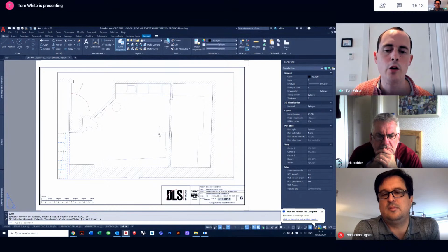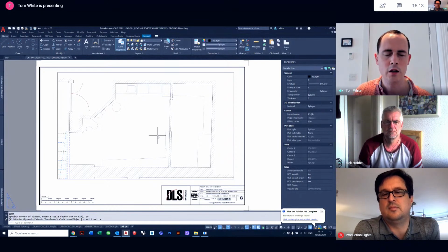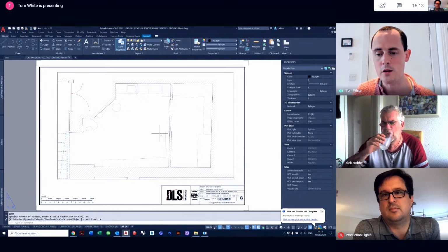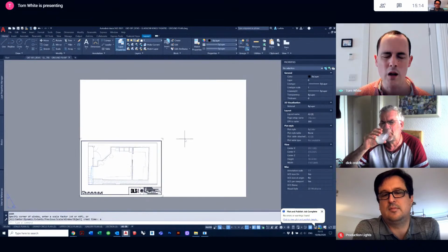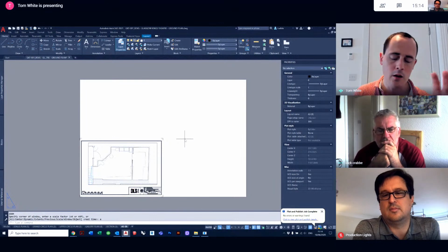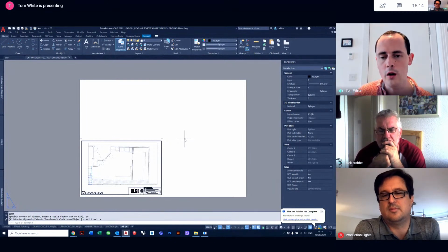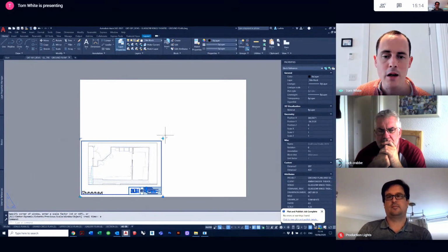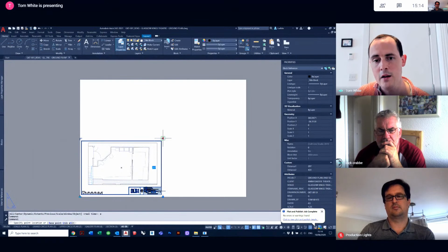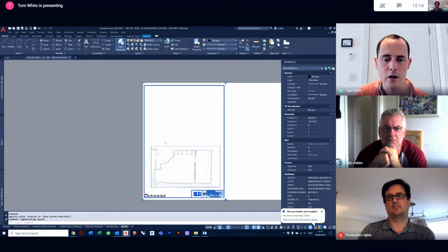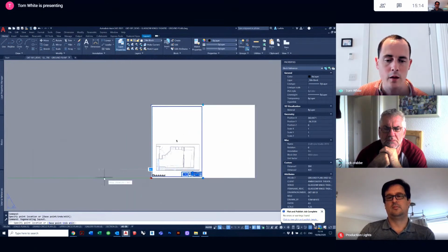And you're like, oh dear, what's happened there? When you do Zoom Extents, you'll only zoom to an object that's on the page. The object on the page is currently an A3 template to print. But if I zoom out, you'll see that the white piece of paper is much, much larger. In this circumstance it's 4 times as big, because an A1 piece of paper can fit 4 A3 pieces on it. So I have made a stretch command on this template, and it stretches to A2 width, A1 width. I'm going to stretch to the left-hand side to A2 length and A1 length.